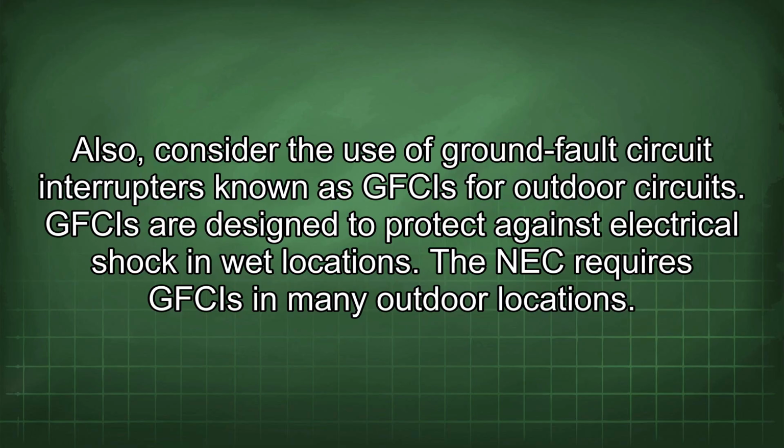Also, consider the use of ground fault circuit interrupters, known as GFCIs, for outdoor circuits. GFCIs are designed to protect against electrical shock in wet locations. The NEC requires GFCIs in many outdoor locations.